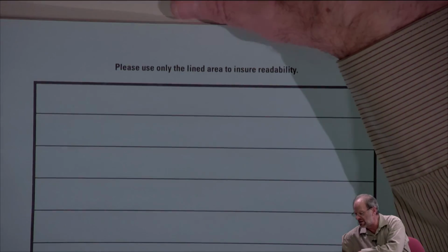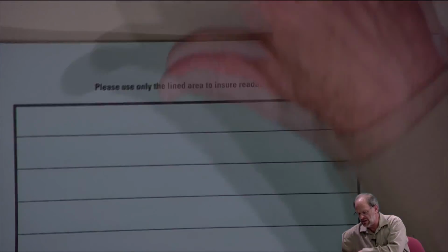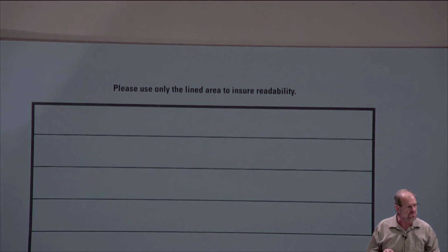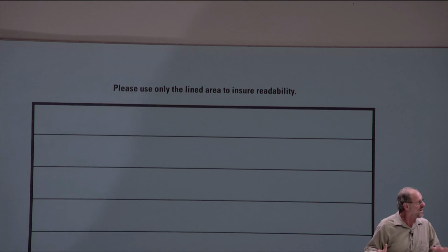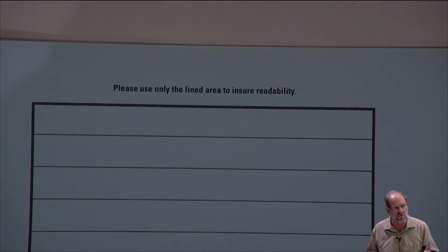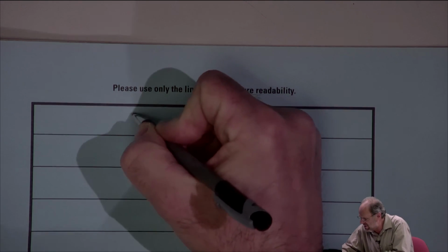Some of these first law problems are going to be involving ideal gases, and because there are so many gases, there isn't nearly as much property data available for this wide variety of gases as we have for, say, the refrigerants or for water. So oftentimes you just don't have property tables like the ones we've been looking at here on the board. We're going to have to use another method, and that involves what's called specific heats.